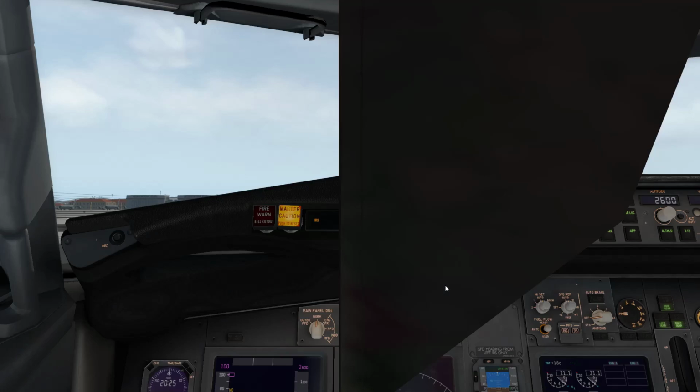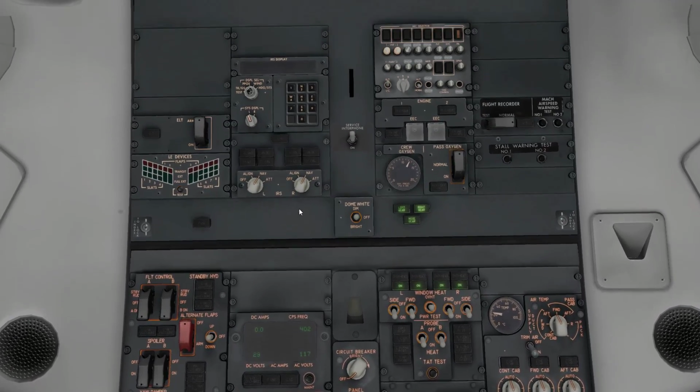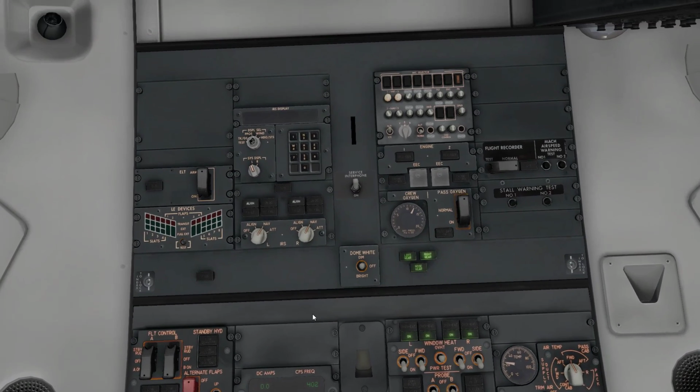I think I know. Going back to my upper overhead panel, at my align switches, you can see we're set to nav and we have a blinking align. Just for the sake of troubleshooting testing, if you look at the IRS display screen by this number pad, the top left knob there, this large section of the knob, you scroll the whole way to the right to HDG STS, that's a status switch, that would tell you how long it would take to set your alignment. Well, our alignment is set. That blink is a caution.